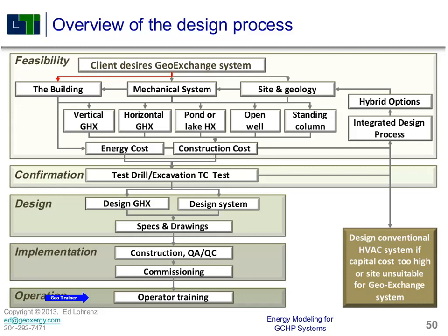Yeah, I think what you're changing is really the borehole thermal resistance on the heat exchanger. Adding more pipe, you're basically adding more heat exchange surface by putting in a coaxial heat exchanger.